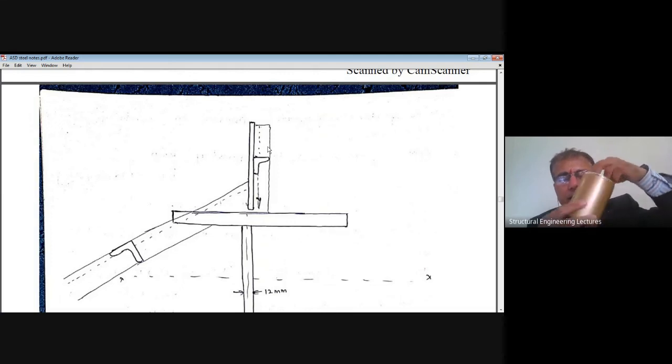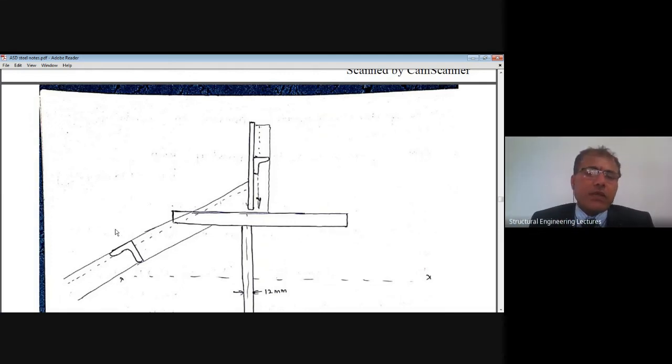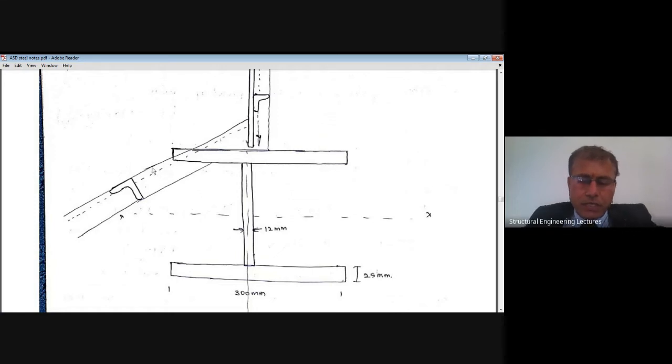of the vertical wall, right? Similarly, in the hopper bottom portion also, we have horizontal stiffeners running at every equal interval of 1.5, 1.5, like this, and also in the perpendicular direction, they are culminating at the apex point of the frustum of the cone, like this, right?